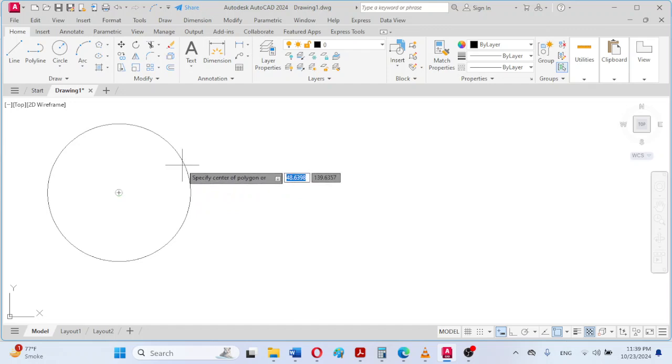the circle, because that is actually the property of the boundary of the circle, and this is the center of the boundary of the circle. So as soon as we click on the boundary of the circle, the center O snap is shown.